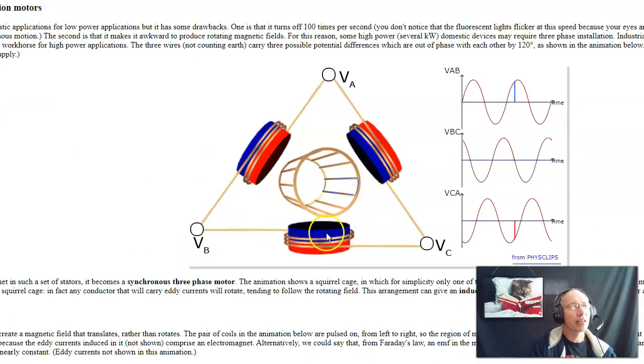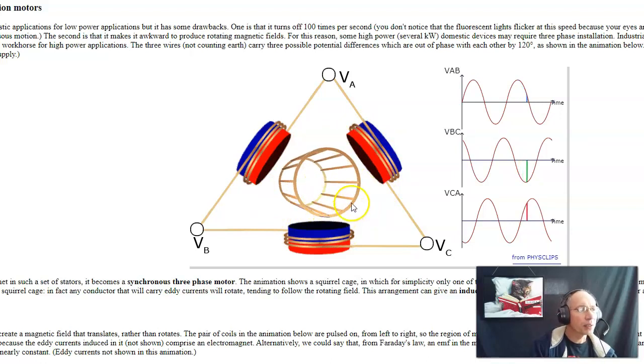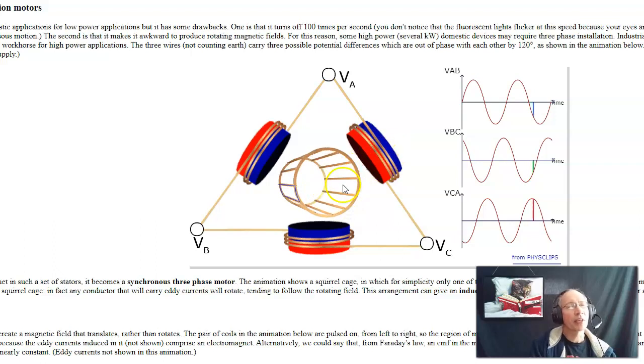If I have three-phase voltages going around the circuit, that produces a rotating magnetic field. This is an induction motor. This is basically a conductor in an iron core. That's a single turn for a motor. If I have an n-to-1 turn ratio, the current induced goes up as n-to-1. So this is 100-to-1, I have 100 times the current.